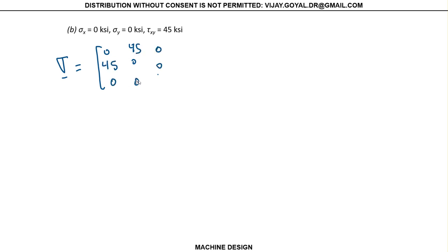Okay, so that concludes the first one. So now let's do this problem. Your state of stress is 0, 0, 45, symmetric, 45, 0, 0, 0, 0, 0. Again, remember the first thing: make sure why we are using this equal to 1, and then find my sigma 1, sigma 2, sigma 3, and my tau max, and then I just work with the theories.